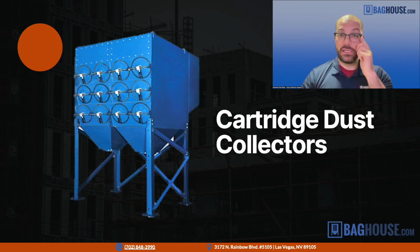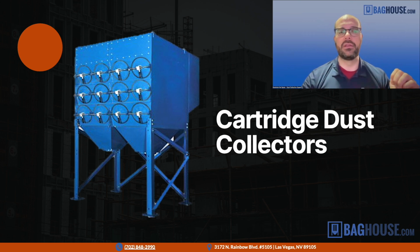Usually we see these retrofitted into existing baghouses, but sometimes we do new systems with them as well for mining and cement. More often they're used when we have bin vents or small systems as opposed to a very large baghouse. But it's absolutely something that you should investigate in some of your applications with someone like us to see if it's a viable option, because there's a lot of benefits to switching to the pleated filters in your baghouse.